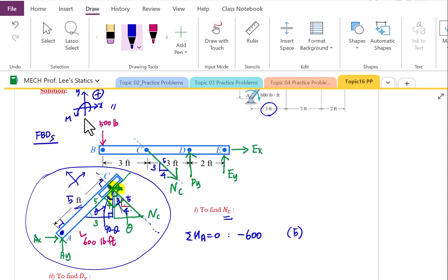And the absolute value, N of C, that's what we have to find. And then let's apply the right-hand rule. Starting from point A, place your four fingers onto the moment arm. We can call this counterclockwise direction, therefore plus. They must be balanced. One unknown, one equation, we can directly find this N of C as 120 pounds. It is positive, meaning the same direction as we set in the free body diagram.